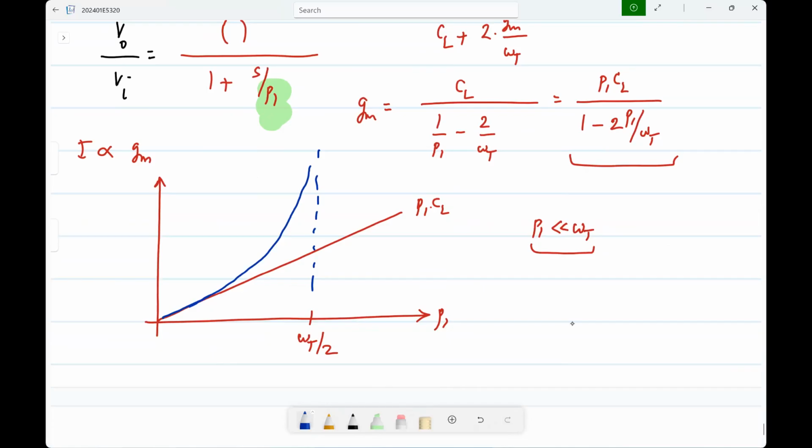The power dissipation will be proportional to the bandwidth. But as you go on increasing the bandwidth, the power starts increasing super linearly, that is, more than in proportion. And you will find that beyond a certain speed, you can't make the amplifier at all, in a given process.